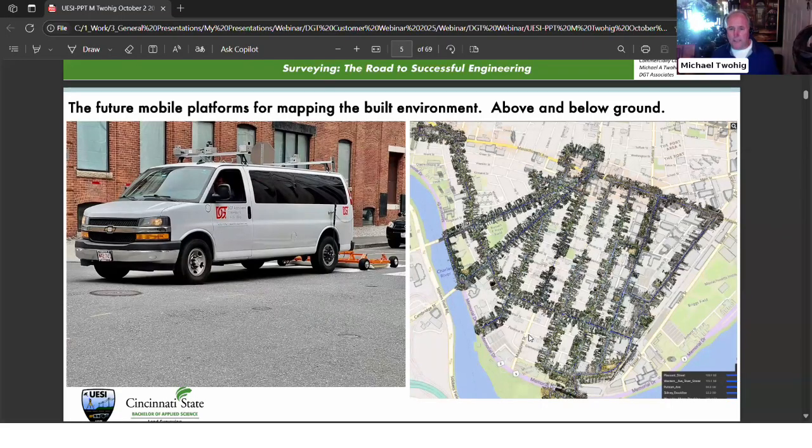So the entire work of picking so many streets at a low level made an awful lot of sense to do a compilation, see what you're dealing with, and then transition over when they started eliminating so many roadways and street routes to get back into final route selection. For us, the final route selection meant that you go from level C and D, low level information, to highly reliable level B. And because we had been doing so many projects in the same time period, very similar to this type of work, we were actually looking at which type of radar system would get us through these.